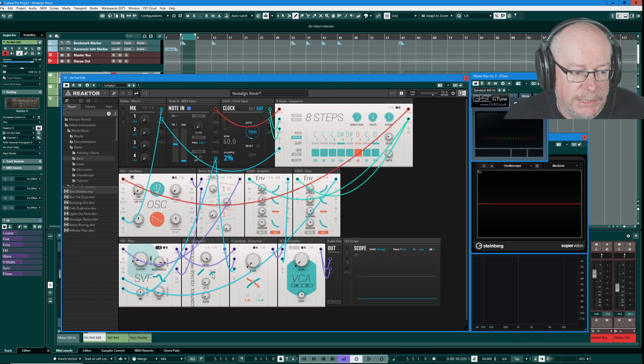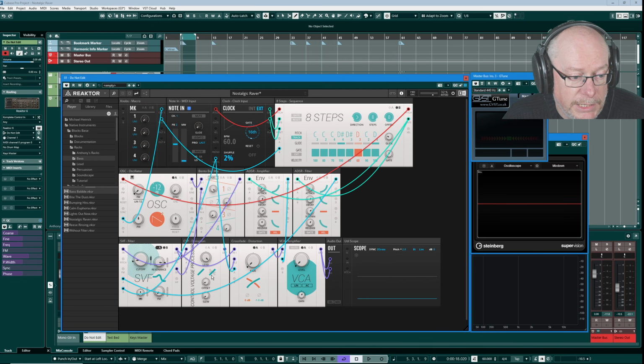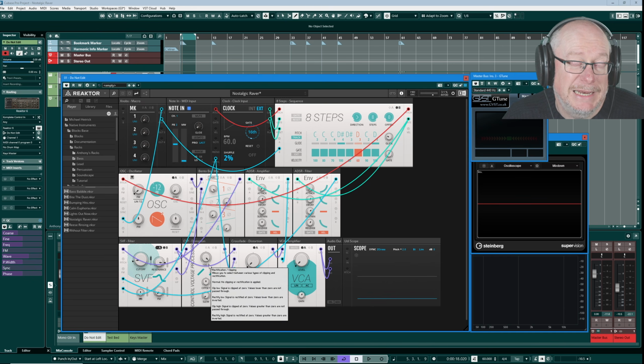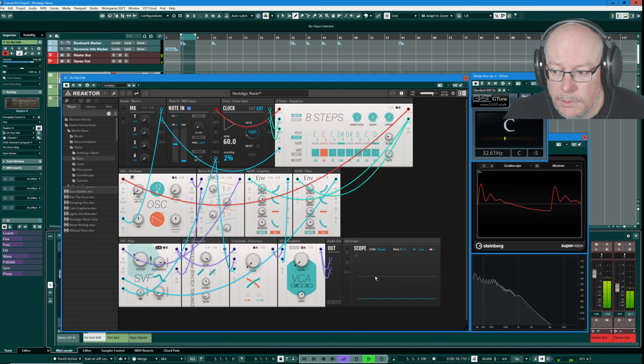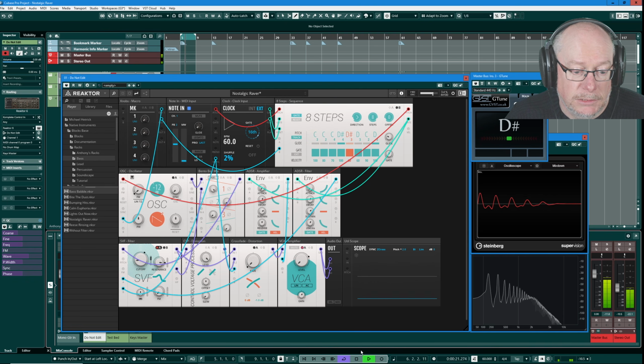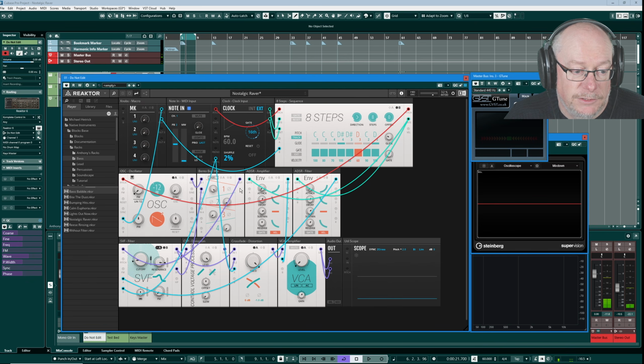What this thing basically does is manipulate a control voltage that's coming into it in one of multiple different ways. In this particular module, this rectification and clipping option here, can you see this shape? Basically, normal mode, if this control voltage processor was going to do no work, it would look like this. So we set our offset to 0 and we draw a diagonal line on this module. In this mode, the control voltage processor is doing exactly the same job as the raw audio that's completely bypassing it. So the left-hand side of this fader, as things stand, is going to sound identical to the right-hand side of the fader.